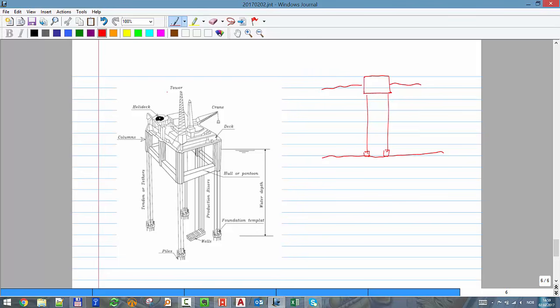But the nice thing is that if, for example, you have waves pushing the structure to the right, so now the structure is here and the cables look like that, you will have a force pulling the structure back into place. That's really the advantage of this type of structure. The force on the line has two components, vertical and horizontal. If you are displaced to the horizontal side, you will be brought back into place because of this force. Is that more or less clear?